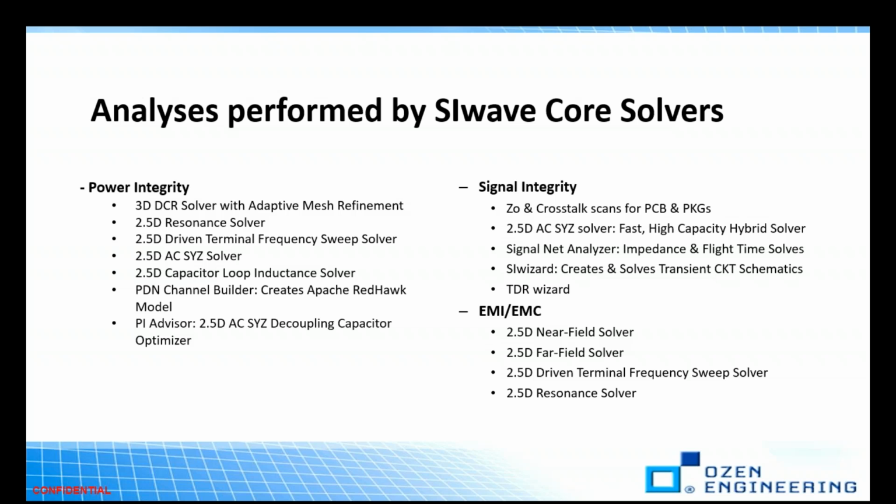First of all, in the electronics products, engineers and users don't need to do the mesh manually. It always creates the mesh on its own, and you can specify the fineness of the mesh, and a number of passes, so that with each adaptive pass, the results refine themselves based on the mesh refinement.